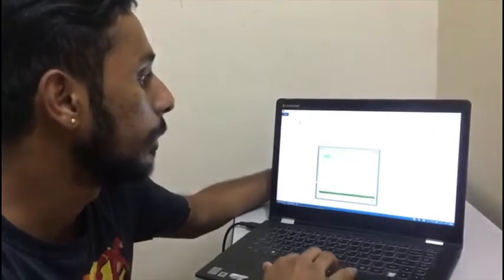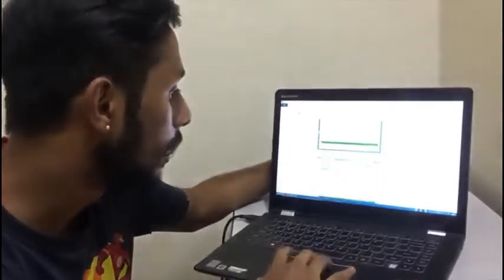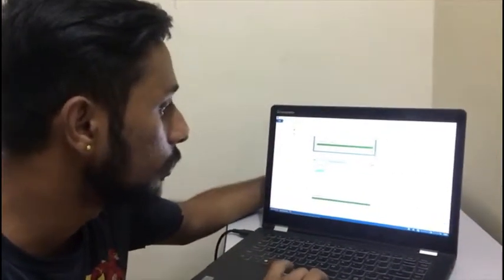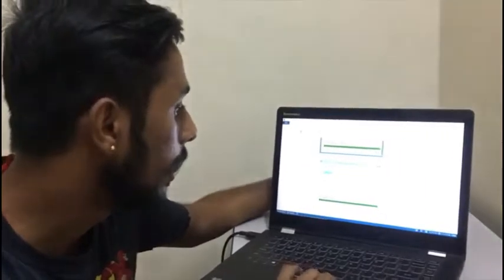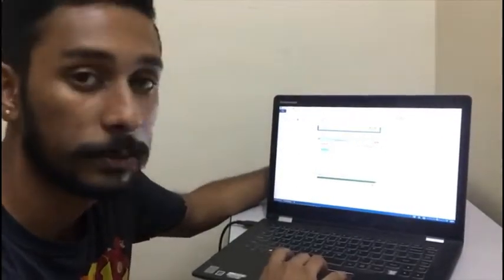So at the final product stream, we have a temperature recorded to be 141.4 degrees Celsius, pressure of 0.9 bar, and a molar flow of 277.4 kg per hour. At the final product's composition, we have ethyl benzene at 0.003058 and styrene at 0.9996942, adding up to a total of 1 molar flow rate mass fraction.